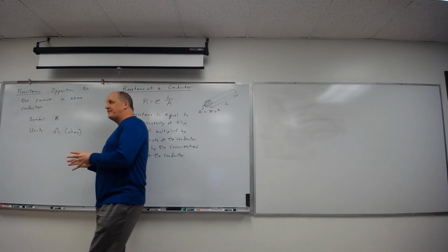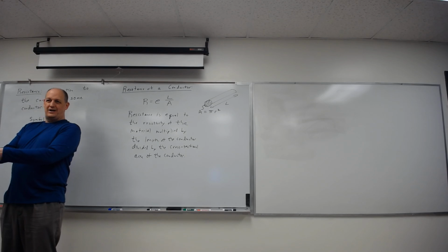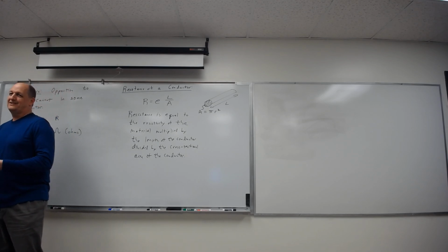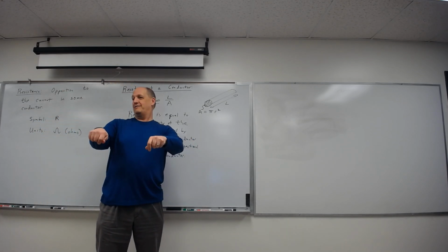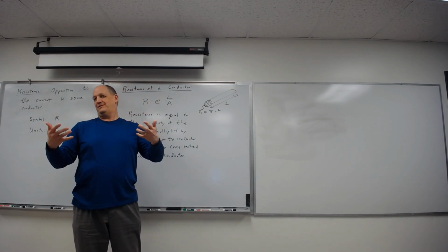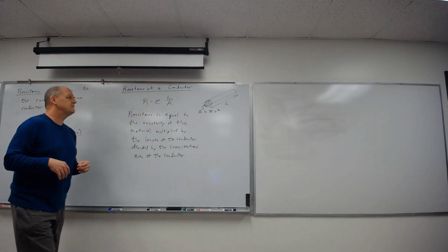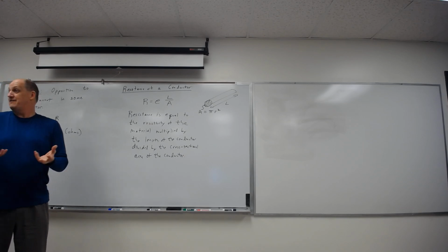Everybody will tell you, oh yeah, get rid of the 14 gauge extension cables, go get 12s or 10s. And all of a sudden you've got 105 or 110 volts across there. Less resistance because it's a bigger, thicker cable. It also has the advantage that when somebody backs a trailer over the top of it, it doesn't break as readily. But that's kind of a side advantage.